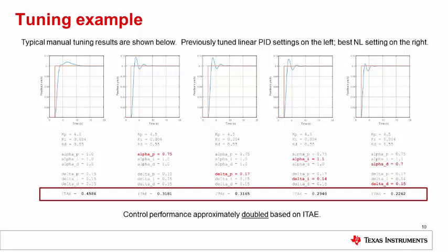in linear mode. We now introduce nonlinear action into the proportional path by adjusting the alpha_p term to reduce the tuning index. Typically a value will be found which minimizes ITAE, in this case 0.75. Adjustments in either direction will cause ITAE to increase. Next, we try to adjust the linear region semi-width parameter delta_p. In this case, a small increase improved the index slightly.